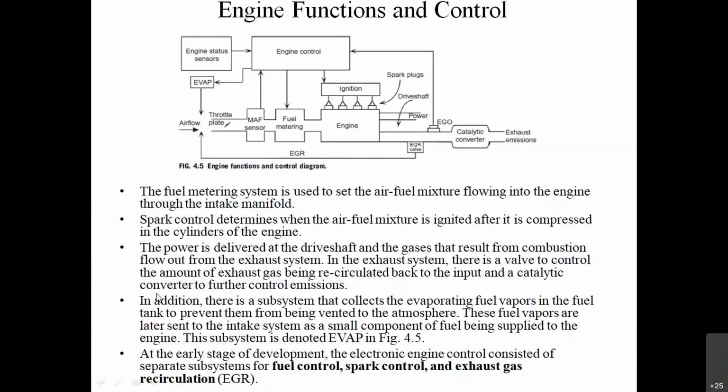In addition there is a subsystem that collects the evaporated fuel. Whenever fuel is vaporized, some of the fuel will be wasted. So that wasted fuel will be collected by this EVAP, the evaporative fuel vapor system, and prevented from being vented to the atmosphere, and it will be reused in our air fuel mixture.